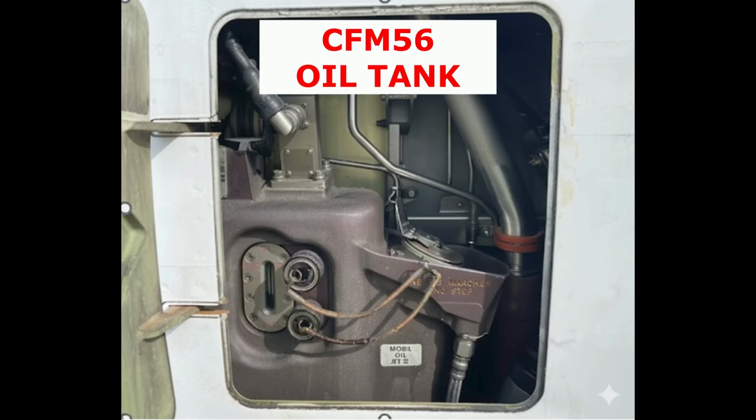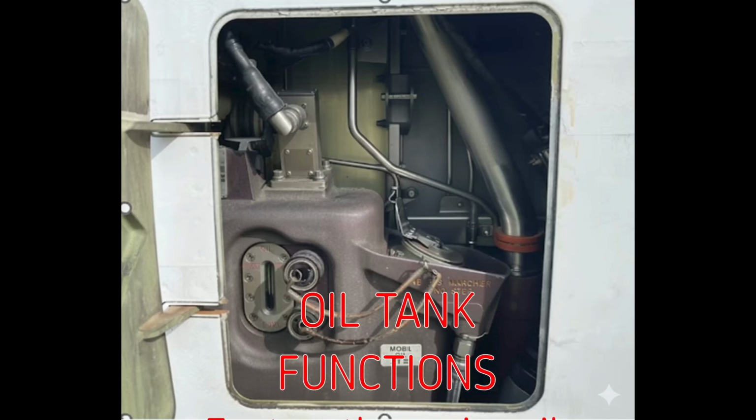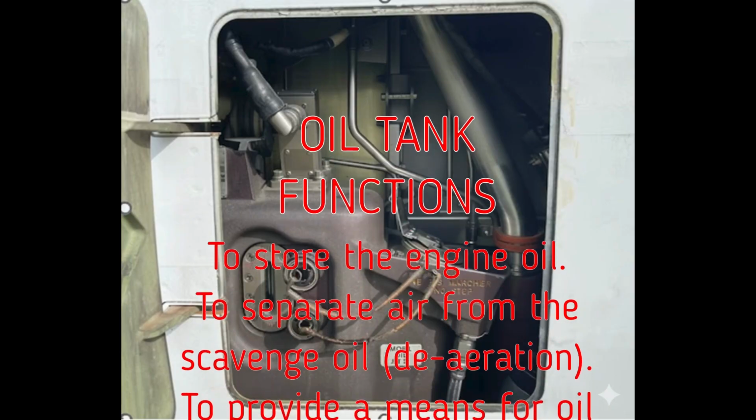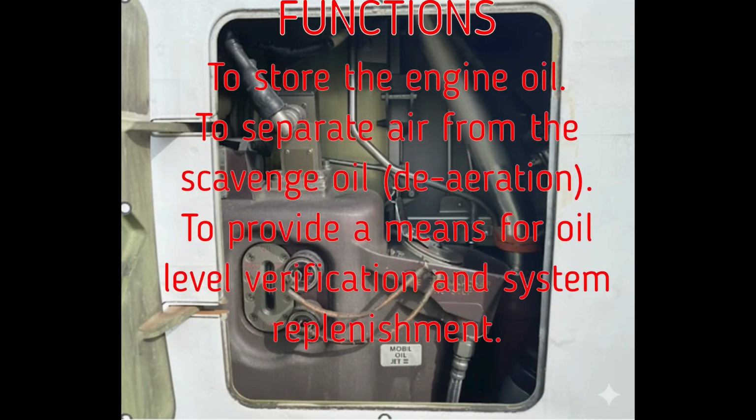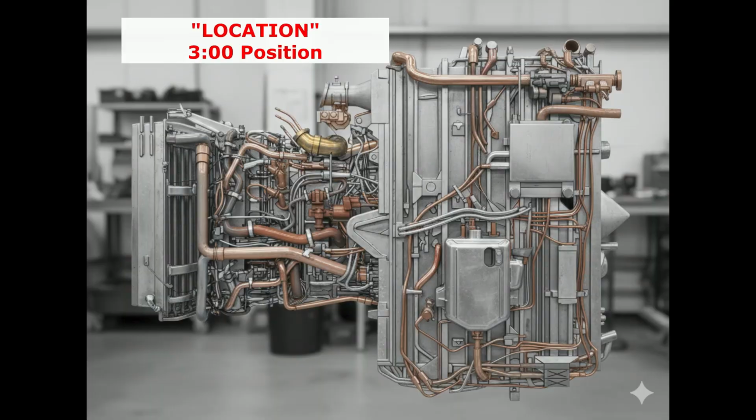The oil tank is a fundamental component of the lubrication system, also known as the oil reservoir. The primary functions of the oil tank are as follows: to store the engine oil, to separate air from the scavenge oil, and to provide a means for oil level verification and system replenishment.